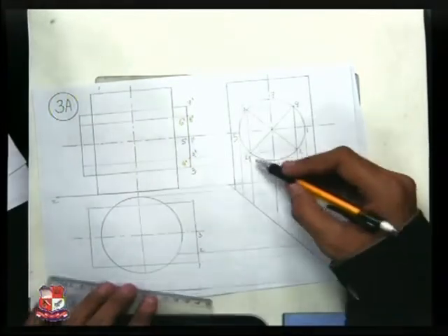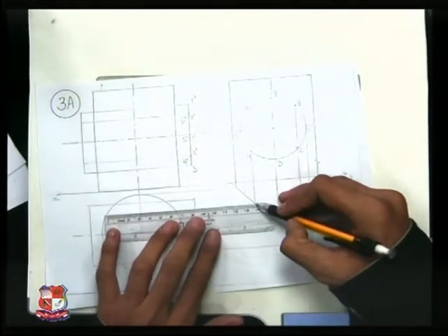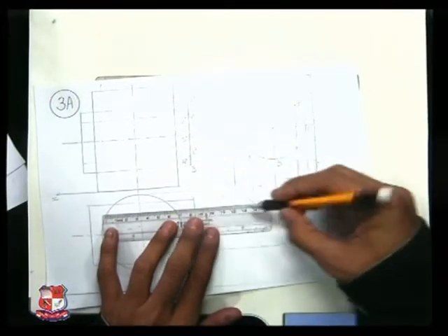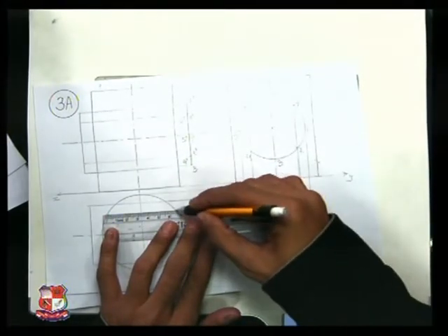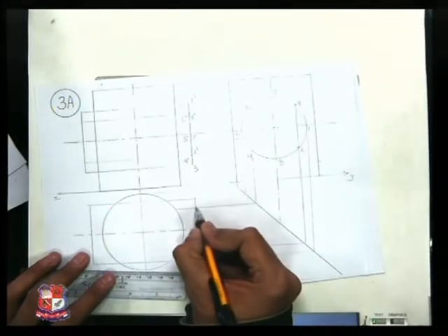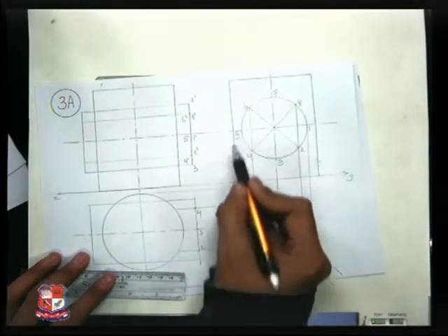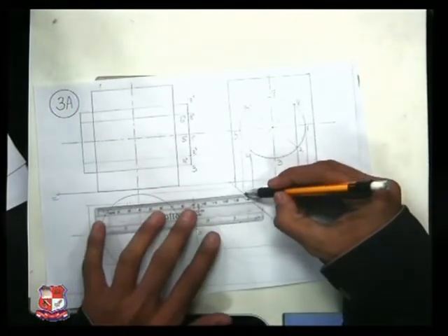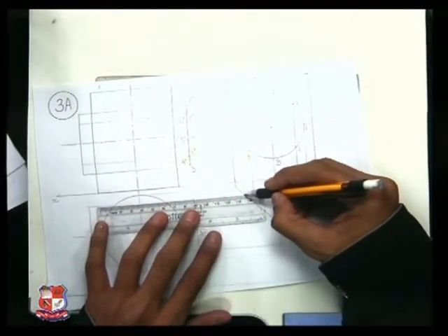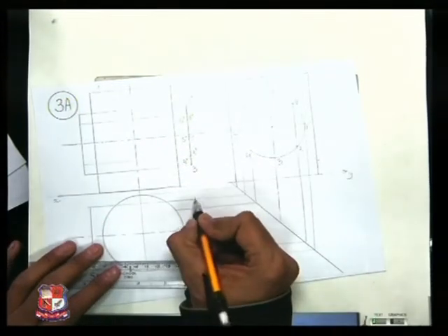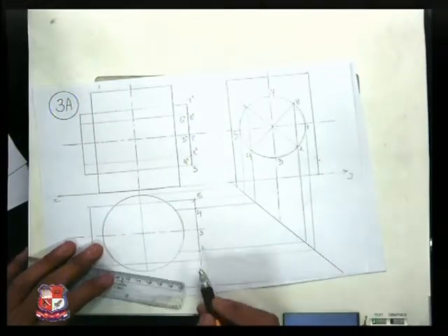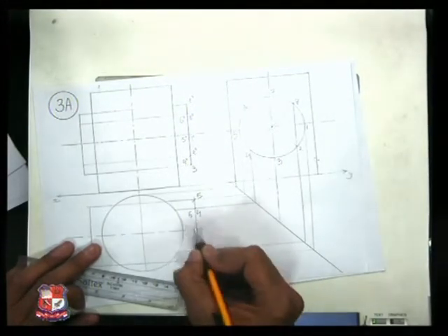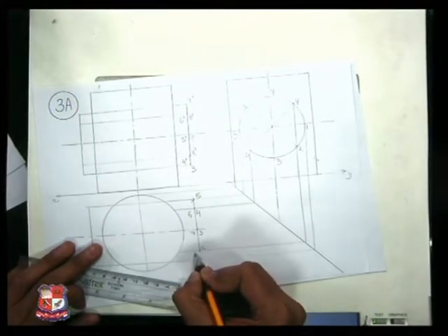From 4, draw a vertical line from point 4 and a horizontal line from point 4. It is shown over here like this, and this horizontal line will cut this vertical line at point number 4. Then from point 5, draw a vertical line. It will cut the miter line somewhere here, and draw a horizontal line from this point. So here is point number 5. So 1, 2, 3, 4, 5. Similarly, point number 6 would be here, point number 7 and point number 8.